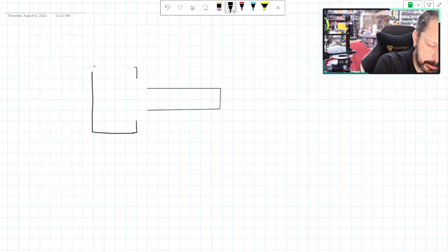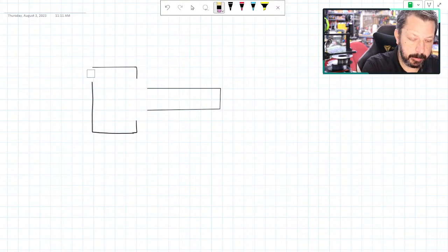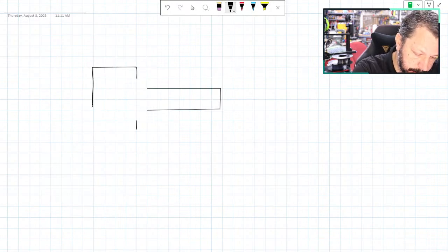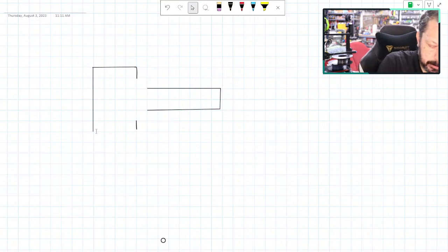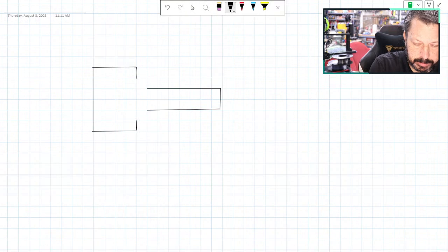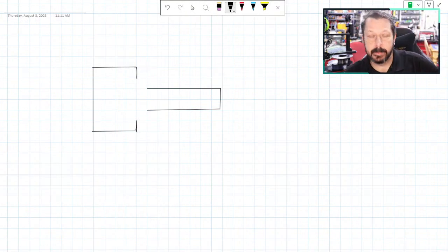That's going to be done a couple of different ways. One way is we could just have a corner. In general, having sharp corners is going to be bad design practice, because the sharper the corner, the more severe that stress riser is going to be. And you're going to get, well, let's look at the little charts. Where would they be?